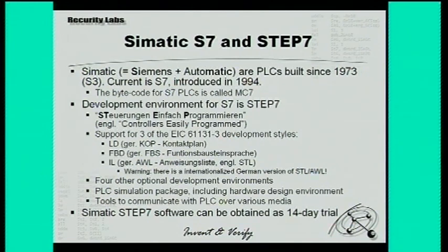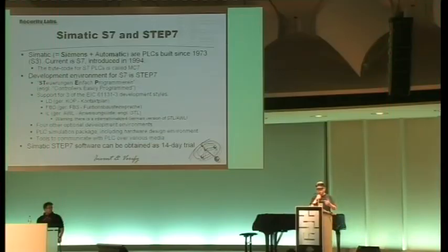So be really careful if you look at Step 7 code, it might be German. Because a German electrical engineer cannot be bothered to understand that AND is A, so they actually have a German instruction set version that has UN for an AND operation. This is why you actually need to know both abbreviations, because all of them are translated.